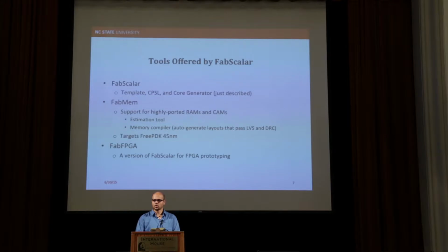So what are the tools offered by the released version of FabScalar? Well, we have already talked about the CPSL and the core generator. Besides that, there's a memory estimation and layout generation tool, and we call it FabMem. Mind you, it's tied to the FreePDK 45 nanometer, so you cannot use other processes with it. It's just for exploration purposes.